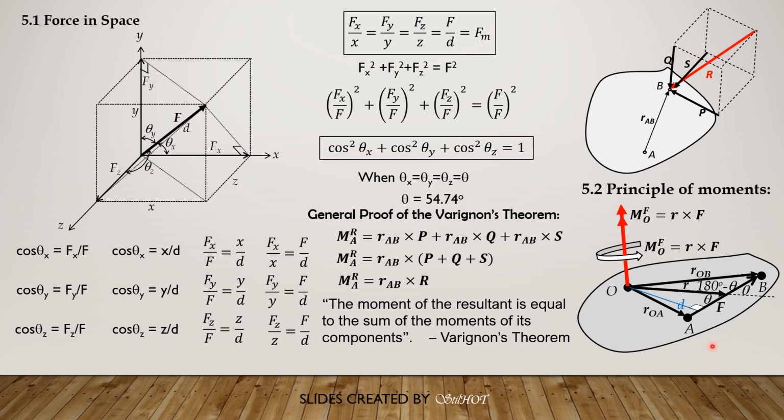So remember that sine of theta and sine of 180 degrees minus theta are the same. Then in this figure here, if we denote R as the hypotenuse, as magnitude, then opposite of R is the perpendicular distance of F from O, and therefore, because this angle is also theta, this perpendicular distance D is R times sine of theta. So D is R sine theta.